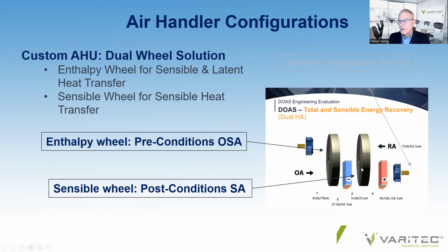The problem with this solution is that you are adding static pressure, so there'll be more fan energy required to provide the air necessary to condition the building. But it is very good, and it eliminates the humidity issue of a mixed air side stream bypass solution.